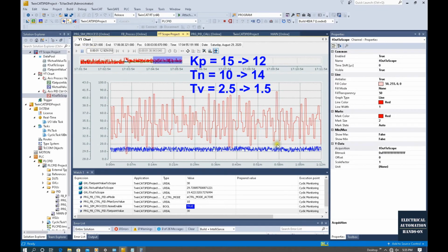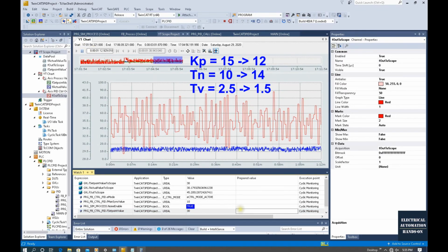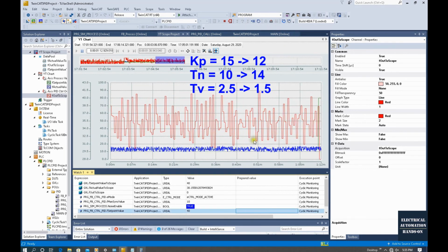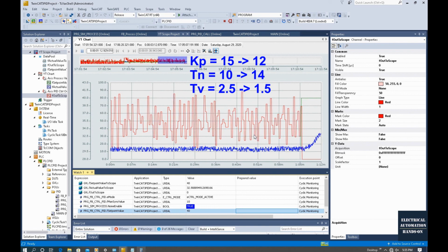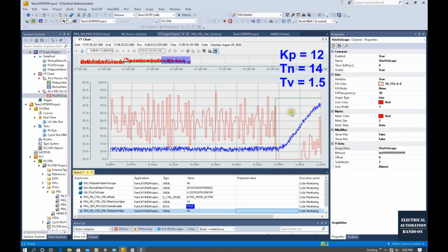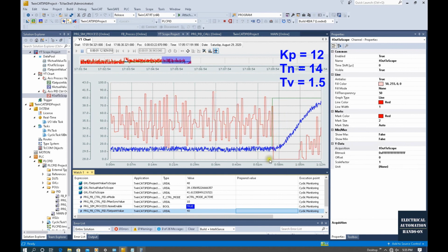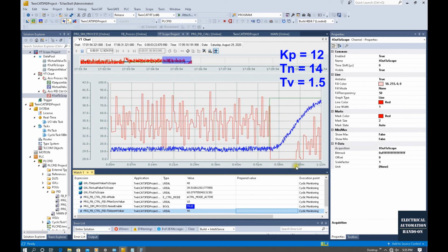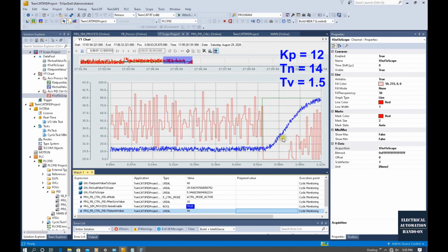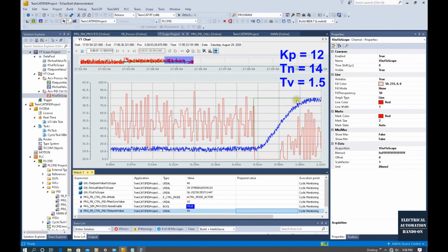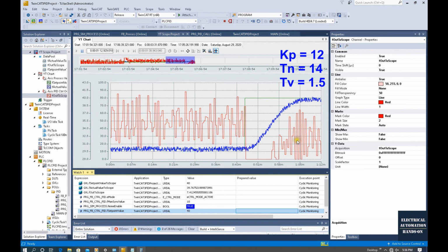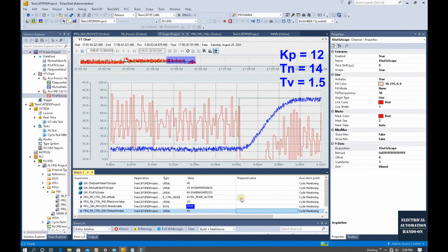Okay, let me start this display, and now let me set 40 again, and let's see this time change. I'm using 5 times speed to show this rising process change, this transition change. So from this area, we can also see the output already go to 0. That means the controller already tries best to increase this temperature. So once the temperature approaches this set point, the controller decreases the output control. The controller adjusts this output under the automatic control mode.